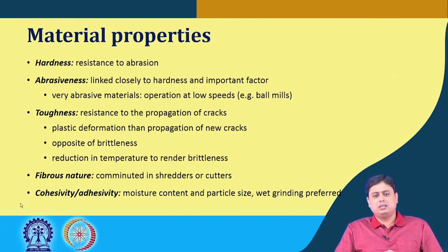So, the discharge or the feed inlet, all these things become a difficult scenario while handling these materials. So, wet grinding in such cases, when handling these cohesive or adhesive materials, becomes immensely helpful for size reduction. That means we have to look into the equipment which can be operated in wet grinding scenarios as well. We have seen the ball mill can handle dry operation as well as wet operation; it can be carried out inside a ball mill.